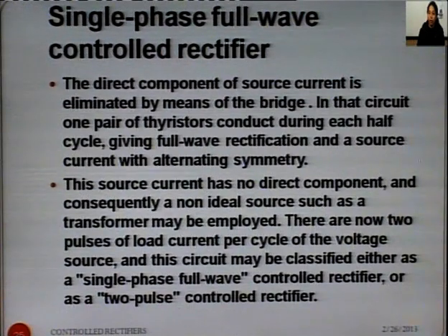There are now two pulses of load current per cycle of the voltage, and this circuit may be classified as single phase full wave controlled or two pulse. We can say it is a two pulse controlled rectifier, one and the same thing.